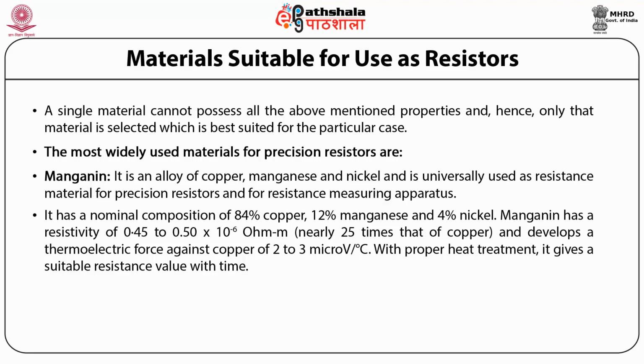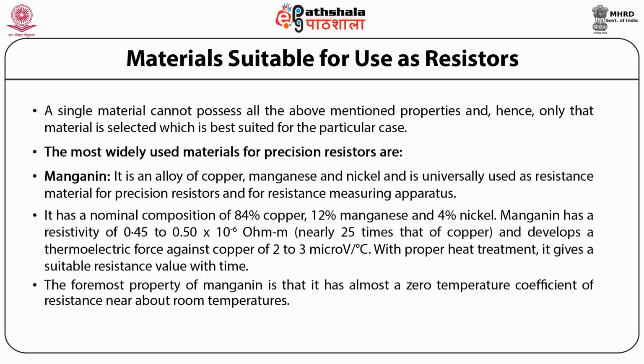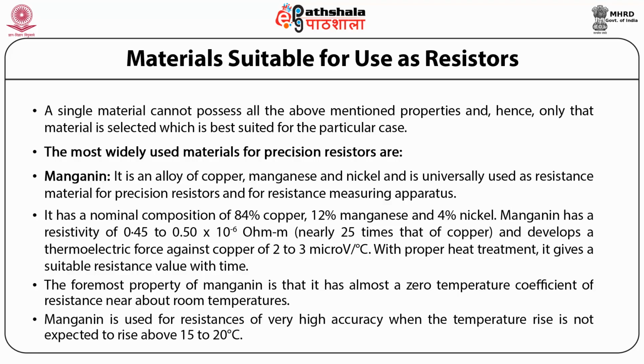with time. The foremost property of manganin is that it has almost a zero temperature coefficient of resistance, near about room temperatures. Manganin is used for resistances of very high accuracy when the temperature is not expected to rise above 15 to 20 degrees Celsius.